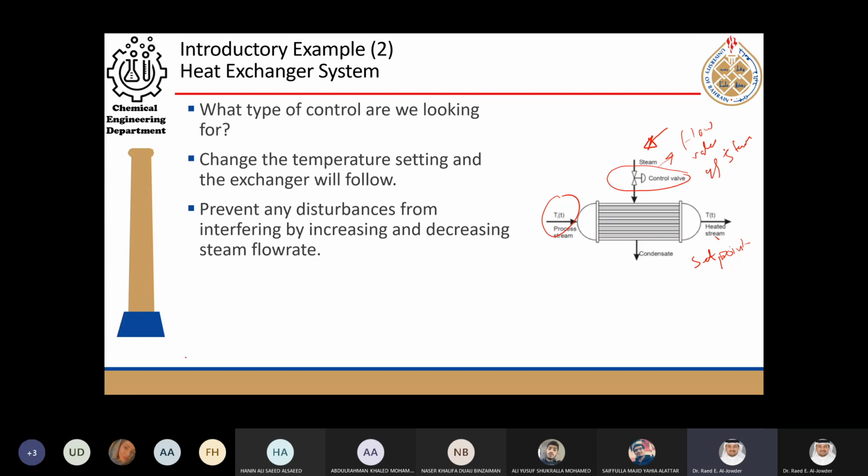Then this engineer replies and says, but I did further analysis and I discovered that if we lower the temperature 5 degrees, we could even get more saving and still maintain the output as it is. So can we operate at 95 degrees? I take this information, I do a calculation, and I discover that what this engineer is saying is correct. So what I will do now is lower my operating set point.